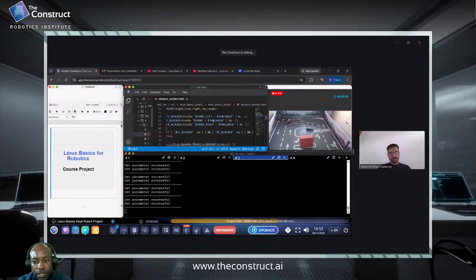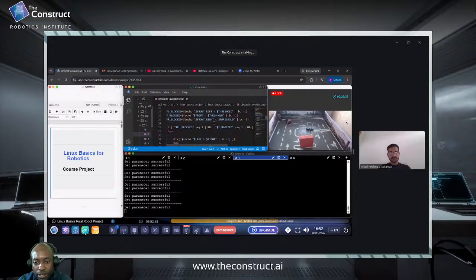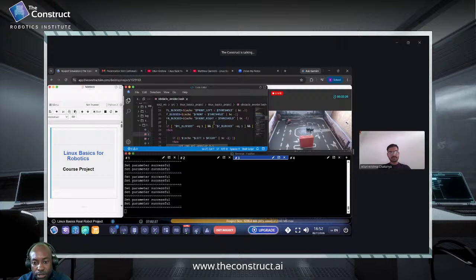However, I would recommend that from now on, do not use any threshold value that is greater than 0.3, so always stick to that. That is 30 centimeters, i.e. 0.3 of a meter. And then for everything else that goes wrong, look at your logic, check where things might have gone wrong. The threshold is actually fine. The worst thing that can happen when your threshold is maybe too little is that your robot will get too close to obstacles before avoiding them, but that's not a big issue.